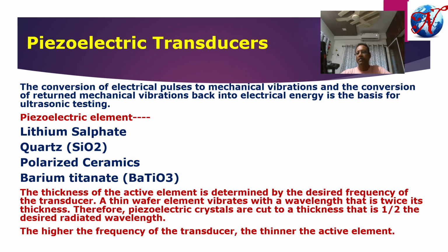We need a crystal which is a good transmitter of sound, a good receiver of sound, can operate at low temperature and high temperature, has a high dielectric constant, is not fragile in nature, and where mode conversion is not done easily. In that scenario, each and every piezoelectric crystal has some advantages and disadvantages.